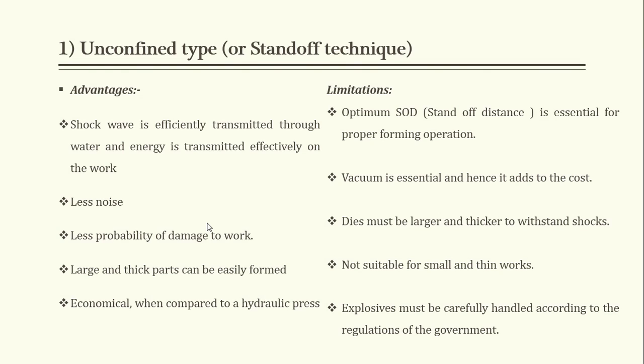Shock wave is efficiently transmitted through water, and energy is transmitted effectively on the work. Shock waves are created by the explosive forming, and they are effectively transmitted through the water medium onto the workpiece. There is less noise and less probability of damage to the workpiece, as we are maintaining an optimum standoff distance. Large and thick parts can be easily worked, and it is economical when compared to a hydraulic press.